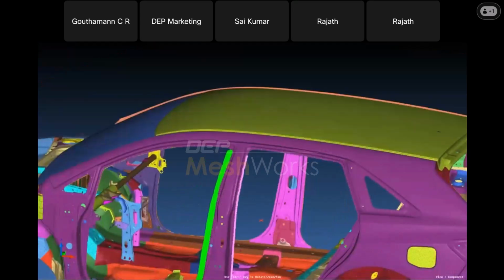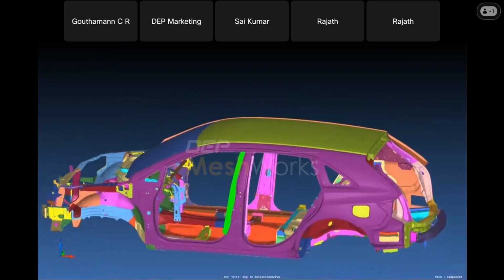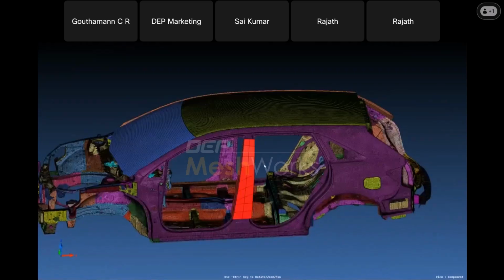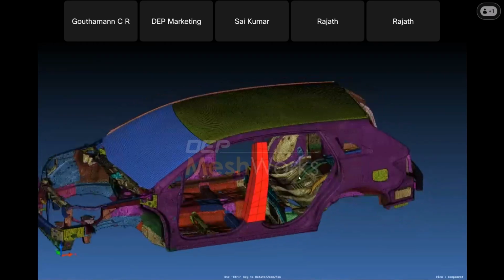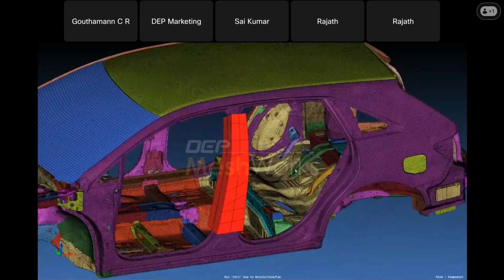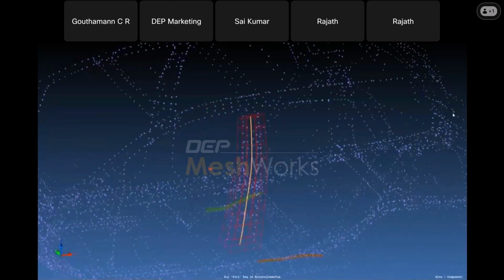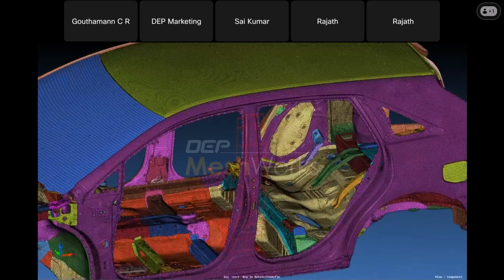And then we can provide an appropriate mesh size and the block size. And then say create block. So it has created a block here. It will create a block and a 1D CAD curve around the block, inside the block.